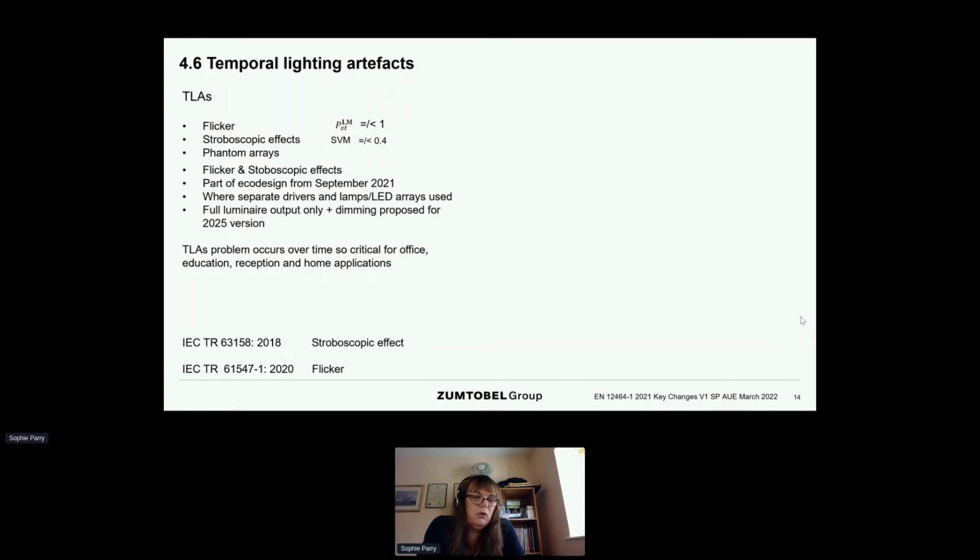But again, you can't do that with LED lighting because the driver is a precision DC power supply with a low voltage, usually DC output. So again, it required a different approach within the driver. So usually flicker and stroboscopic effects are engineered out within the luminaire's driver. Sometimes you can get flicker introduced by noise on the mains wiring feeding the luminaires.